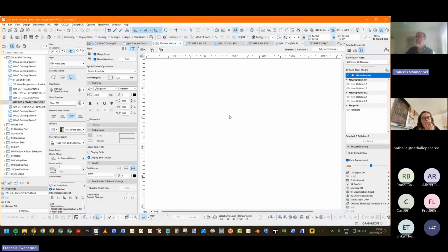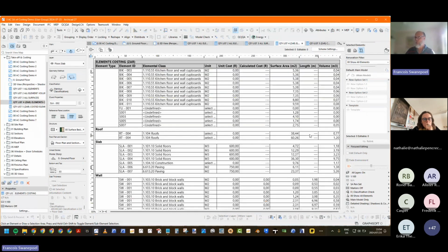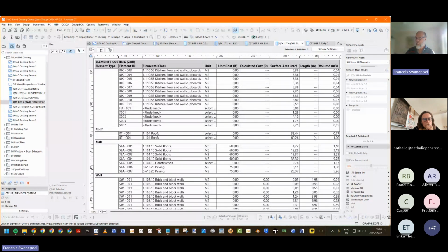And we go back to that schedule, go back to those slabs, you'll see that those are then designated. And here's one that's missing. That was the roof slab that was assigned, and it's also a concrete volume type element that we'll calculate at. Doesn't matter what we put in here now.